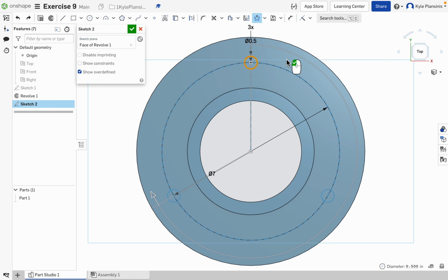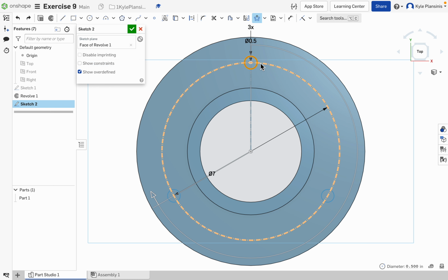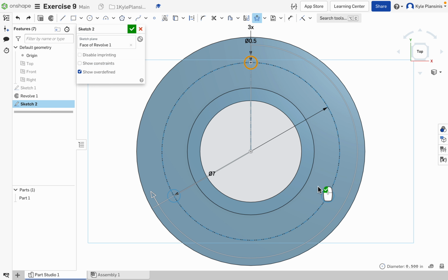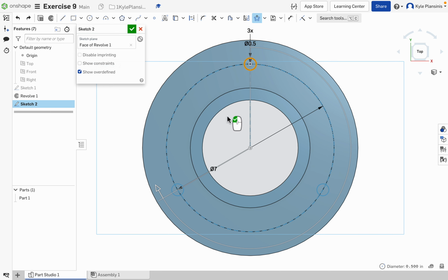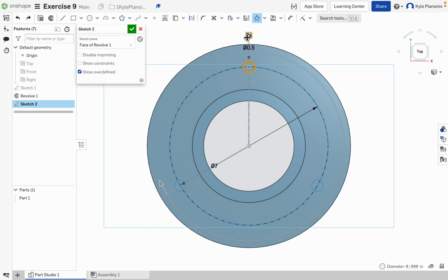If we didn't have these construction lines, we would have to define those things. So you can see here, there's a couple bits of information that it does give us. It gives us 3 times, and then it shows us the direction that it's rotating. So we're going to first double click where it says 3x, and there are a total, including the one that we already drew, of 8. So I hit enter. So now it's showing me that it's going to sketch in 8 of those.